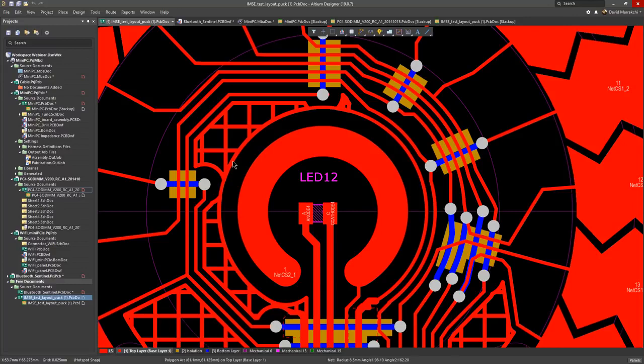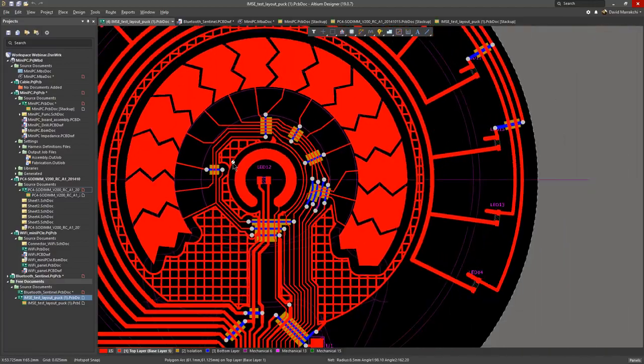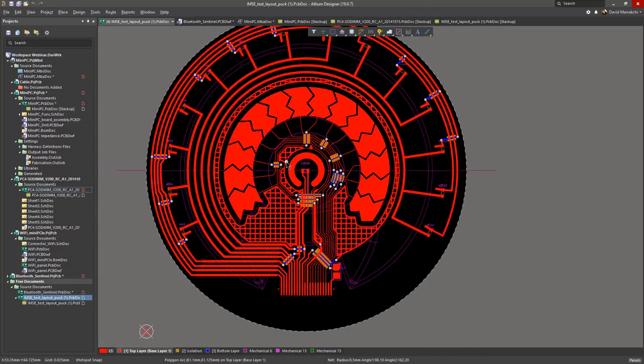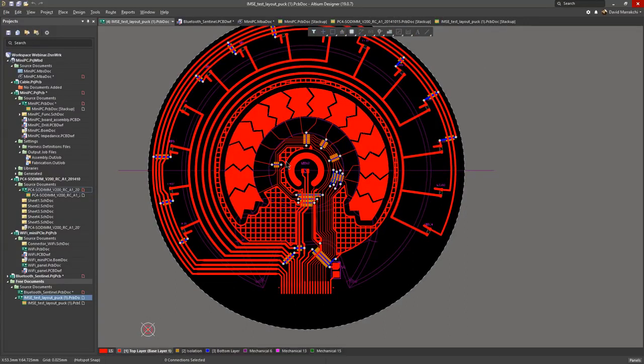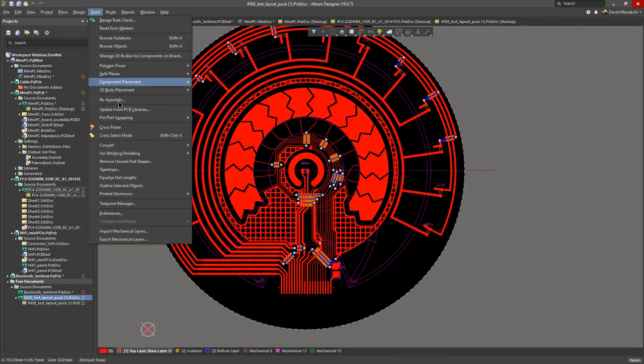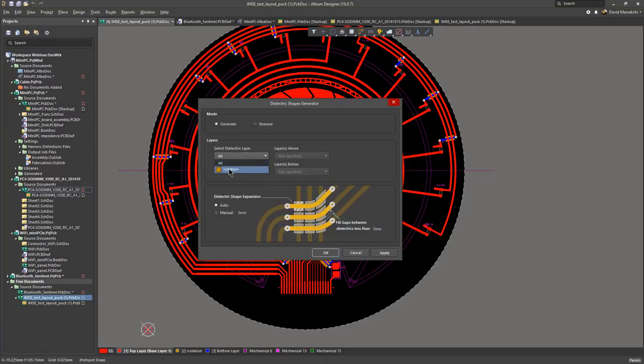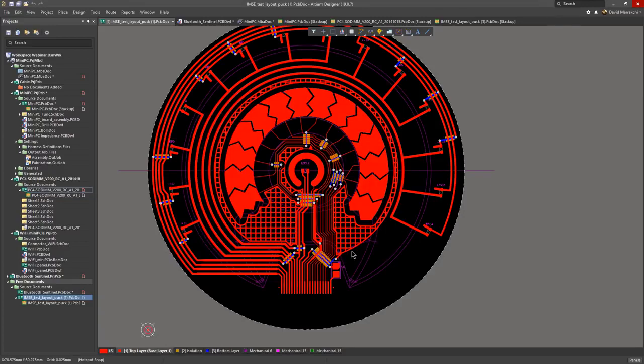It knows that this is a printed electronic design and will flag traces that overlap as shorts within your design rules. And the way to mitigate this, Altium Designer 19 with this new printed electronic tool that we pull from here can automate the generation of these isolating patches throughout the design. Something that would take a very long time manually and can be prone to errors. Of course, there will be something that they will forget, or a patch that they will forget.